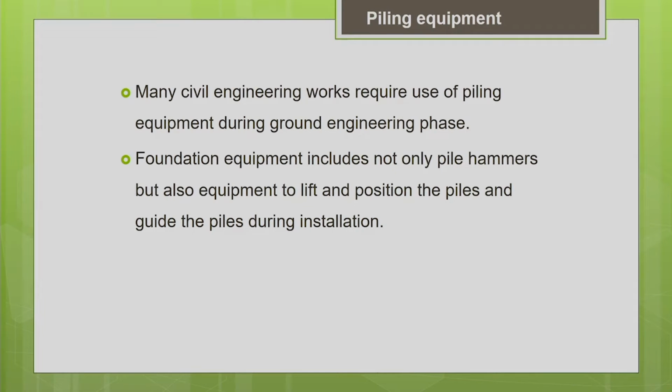So, let us now see what are all the piling equipment needed. The pile hammers are not the only piling equipment; we need a lot of supporting equipment for the pile driving operation. Like you need the cranes to hold the pile and the pile hammer and also to hold the lead, everything in the right position. For holding it and lifting it, we need lots of supporting equipment.